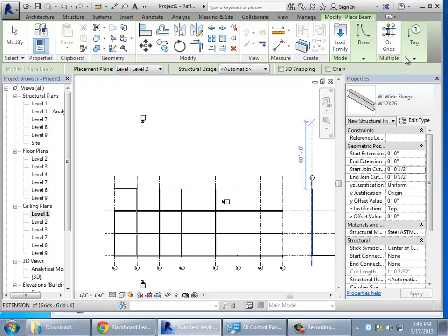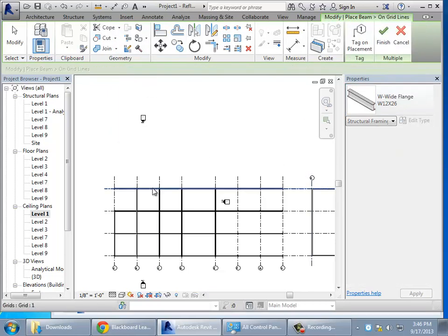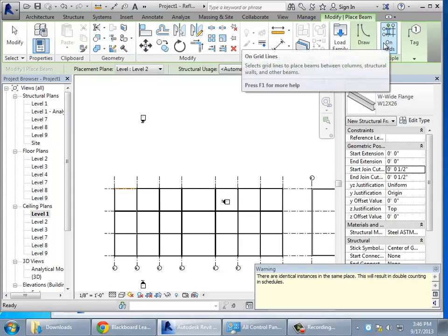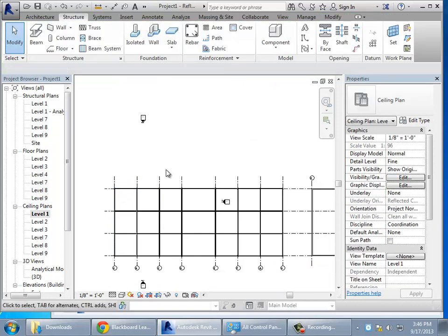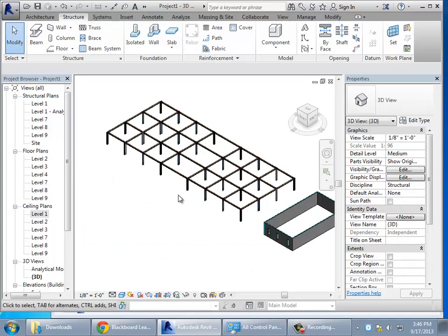Remember to do that. I'll go back and grab these grid lines. And what I'm expecting to happen here is it should complain a little bit about my overlaps. That's okay, I'm ready for that. Just like that one, an overlap in there. Okay, so hopefully now we've got some sort of structure that looks pretty good. See if you can get yourself something that looks like that, with just some basic framing elements in there. You can try to change the size of those things.